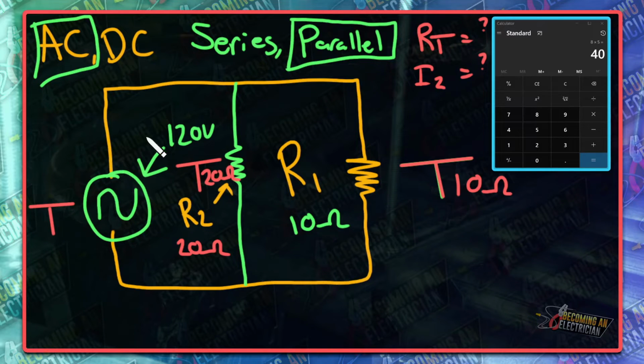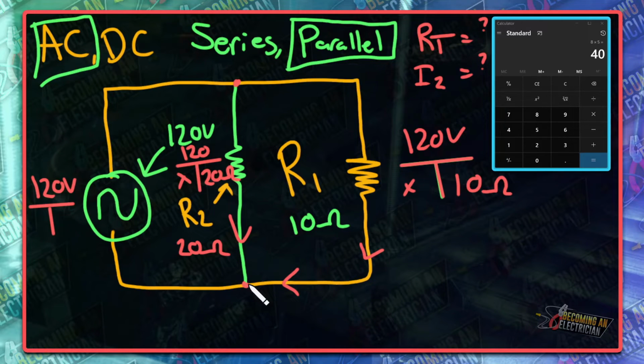Now, when we go to our main, I told you when it comes to a parallel circuit, our voltage stays the same because again, there's no resistor right here. So in other words, we're splicing on, and so this is getting 120 volts right here. And then this is getting 120 volts right here. And so all you have to do is just do the math. And I told you that once we find this amperage and this amperage, which is going to come down here and come down here, what happens right here? I told you that they get added, which means that we will be able to find this value. Once you find this value, we can find this value, and then we will be done. We would be able to answer our test. And so that's the whole trick to these circuits.